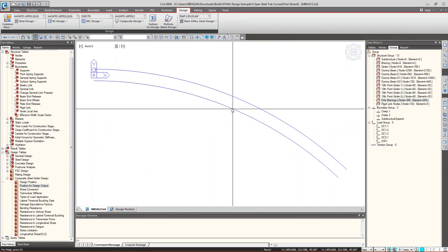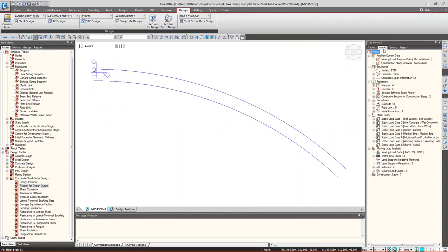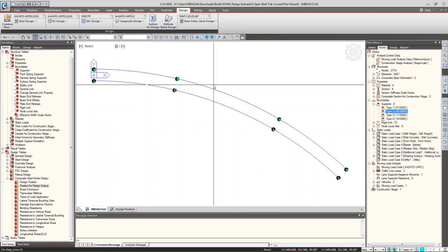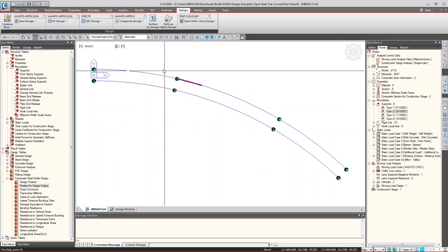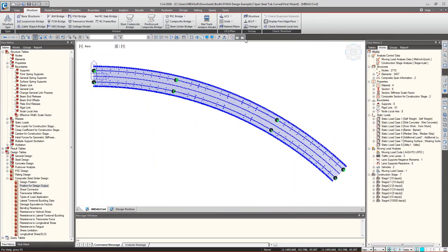So you can activate the girders and you can choose spans in between. So like if I display, I can choose this span, complete this span, and I can go to structure, go to the pre-processing mode to do that.